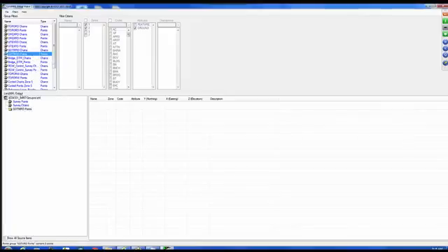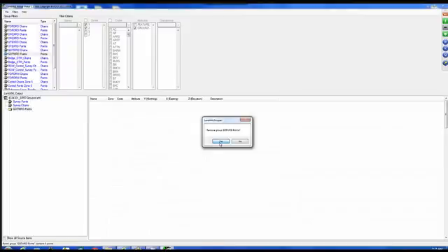So now what I have is my LandXML output. I now have a group called GDTMRD points. So I'm going to pick on it. And you'll notice I can pick all day. There's nothing there. The reason is because the filter was looking for Zone 1 and Zone 2. We don't have those options. So I'm going to remove the group by right-clicking.